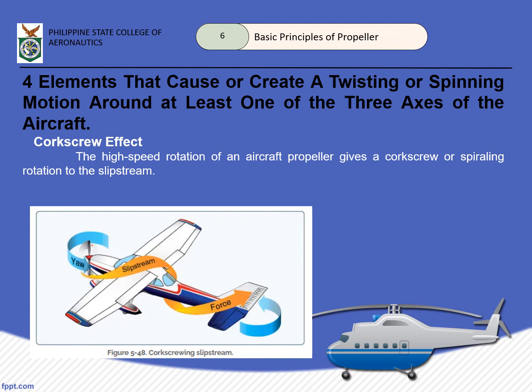So, how does this happen? When our propeller rotates to create thrust, of course, some of the wind tends to spiral around the aircraft, evident in our picture. This is called the spiraling slipstream. And as this spirals around, it eventually will hit the left vertical fin, which causes the aircraft to what?